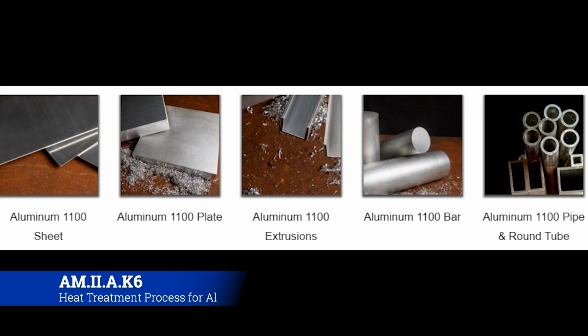But we're going to start talking about the type of metal that we actually use, and almost all the time it's going to be 1100 aluminum. Now, when you say the 1100 alloy, that's simply saying it's commercially pure aluminum. It's aircraft grade, ready to go, all that good stuff. But it's going to come in different forms. What you have in front of you are the different forms you can get aluminum in. If you were to call up 1-800-aluminum and order it, you could get sheet aluminum.